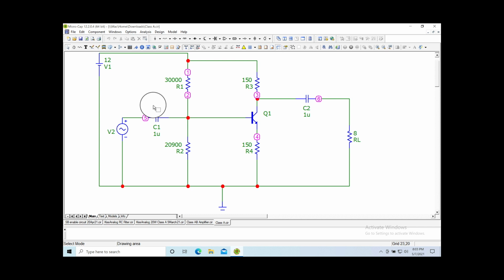We're going to play around with this, and first I'm going to fix it. I don't like the four-way intersection. It's a bad habit to get into. For small circuits it's fine, I guess, but as you get bigger circuits, it's harder to tell when you print out. It's just hard to tell when you're crossing whether it's connected or not. So let's also come up here and make that line the same. Whoops, let me grab this guy, pull it down. Okay, so just clean it up a little bit. The other thing, this number 3 is right on top of the node name 3, so just push that up, and there we go.